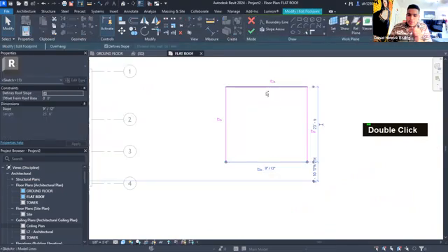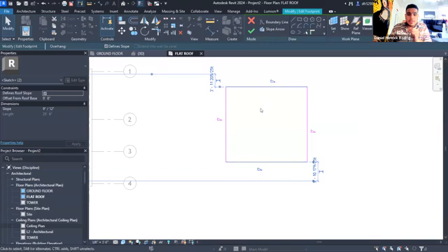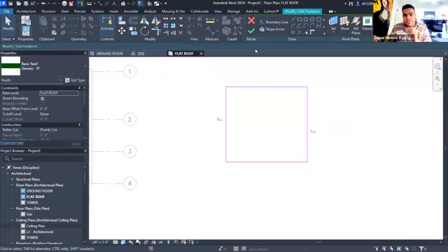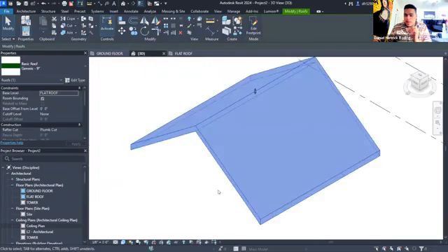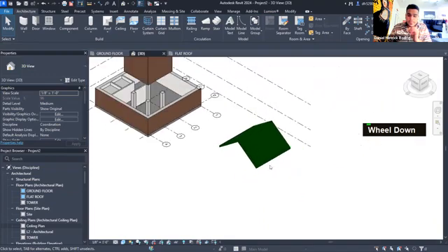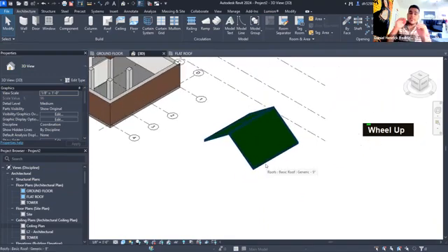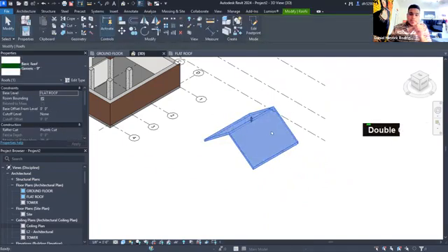If only 2 of these sides were sloped, and the way to select or unselect this is either here on the properties or on this little button here, then you're going to have a gable roof, right? So you just have to see, if you apply a slope to a side, it's going to go up, and if you don't, there's not going to be anything there. So in this case, there's only a slope on each of these sides, and that's why it ends up being this way.